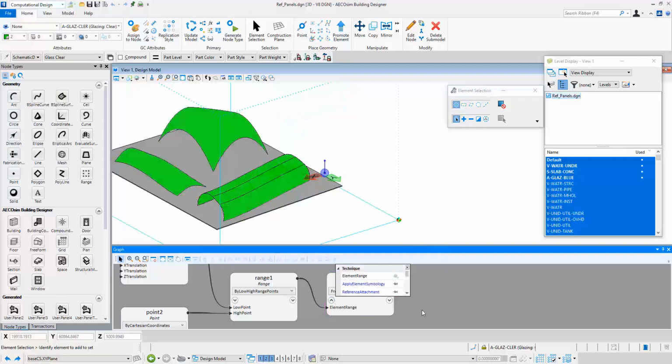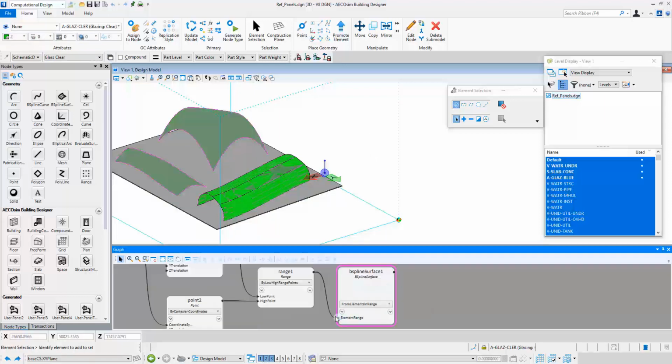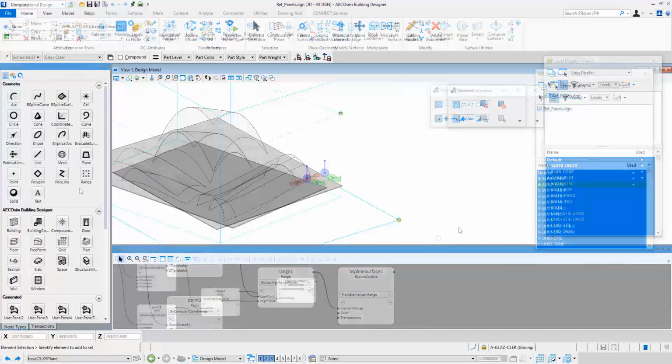Now, did the color change? Because my default color is up there and looking like that. So I can actually force color and other attributes of these objects. So for example, I might force a, where are we? Down here, general. I might force a color, and I also might force a transparency. So I'm just going to turn those two object types on, and we might make this one colored white, and the transparency we can have, say, at 50%. There we go, so they're back to being transparent.